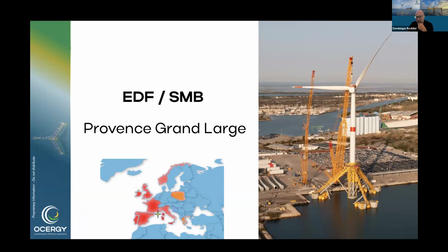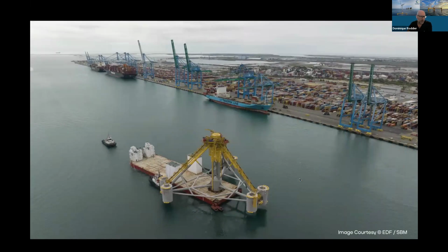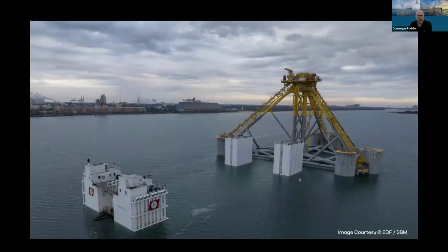This one is a tension leg platform. So it's not anchored, it's tethered to the seabed. This is the assembly of the hull. Here you see the hull with the buoyancy modules that pull down, so you have ballast in those tubes. They put water into it to lower the platform, and they remove the water, hence putting tension on the tendons. And I mentioned, so same thing.